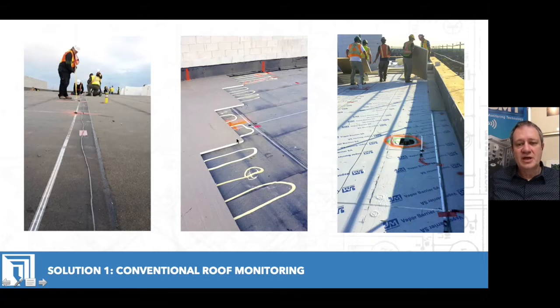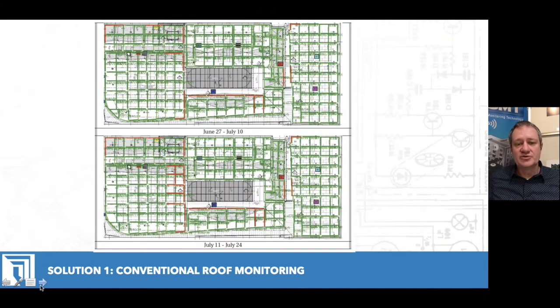Conventional roof assembly: these moisture detection strips would go down on the air vapor retarder underneath the insulation, do perimeters and penetrations, and we're able to get what the moisture level is within this particular structure. A sample of the output, once it's gone through data acquisition and through our visualization tools, is shown here. The red areas are considered wet detection strips, and we start comparing different timelines, different building components, and we can point to the areas where water has intruded within the conventional roof assembly.